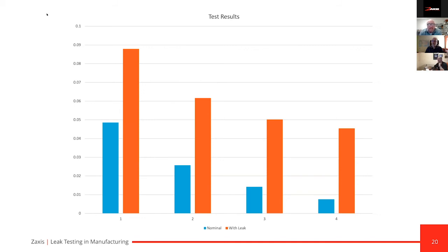Once that's live and running, you can just simply turn a dial and watch a reading on the screen so that it will get to your achieved test pressure. In this case, it was 10. So I blocked the port with my thumb and then turned the dial on the regulator until the readout read 10 PSI. Then I knew the regulator was physically set in place in the case of a manual regulator.